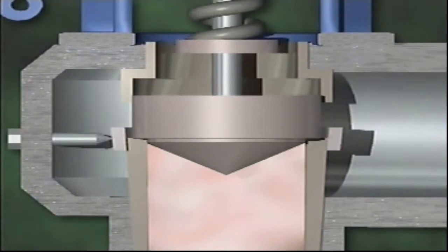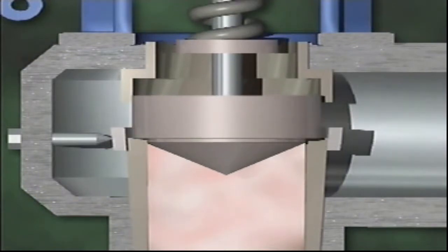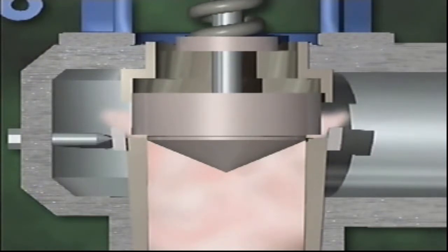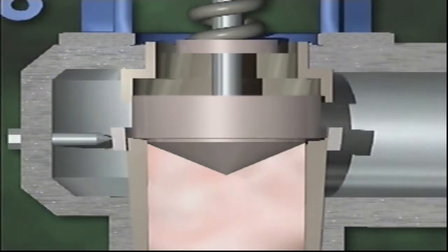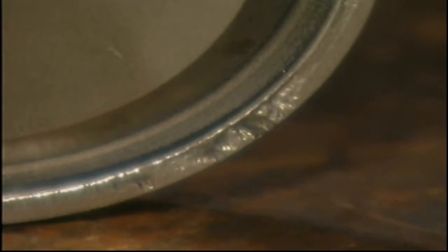Adequate blowdown helps prevent a condition called chattering. You see, if there's no difference between a valve's popping pressure and its seating pressure, the valve disc will jump up and down on its seat until pressure either increases enough to pop the valve open again or decreases enough to keep it closed. This condition is called chattering because of the sound that the disc makes as it moves up and down. Chattering can seriously damage both the disc and the seat because it promotes steam cutting. Steam cutting occurs when the velocity and the temperature of the escaping steam are so high that the steam cuts into the metal of the valve's disc or seat.